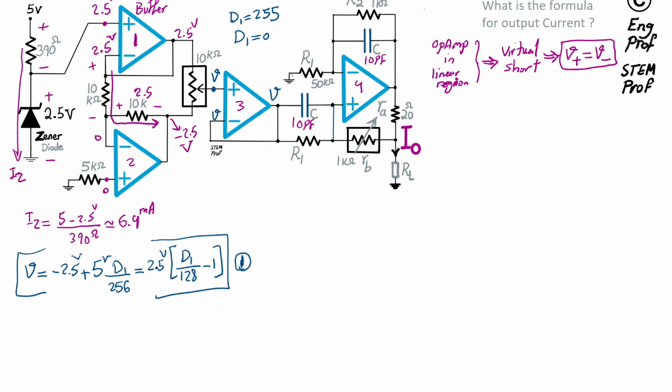Okay, so let's move on to the next computation we need. In this, voltage V appears at the input of the last stage. Let's refer to the voltage at the positive terminal and also the voltage at the negative terminal, which should be the same because of the virtual short for the final op-amp, as Vx. So we have Vx at the positive and negative terminals. We can neglect the cap because, as I said, for our analysis, the caps are not important.